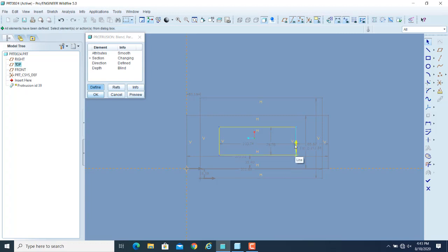And this is basically the direction, and suppose you want to change the direction of those point sequences. Again, the start point, if I click that point, the methodology remains the same. First you have to select the point, so I will select this point, and then I will place the cursor and right click, and then if I again click on the start point option, you will change the direction.